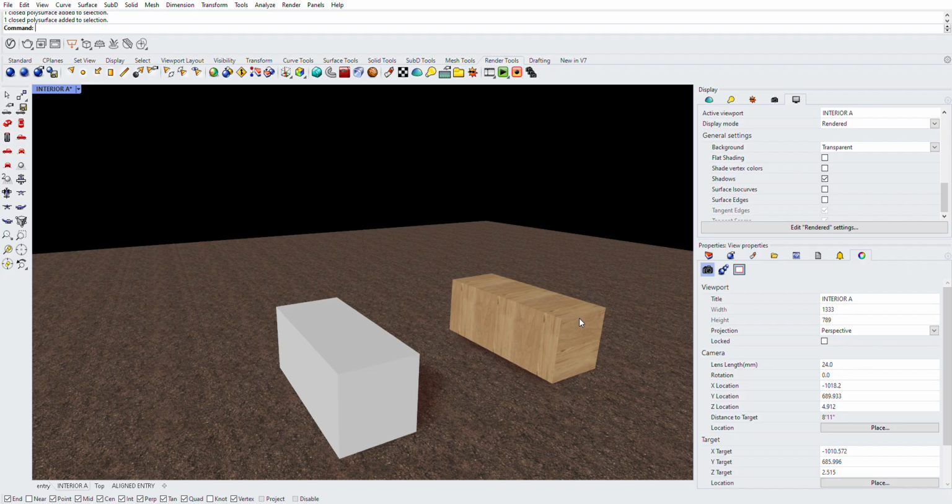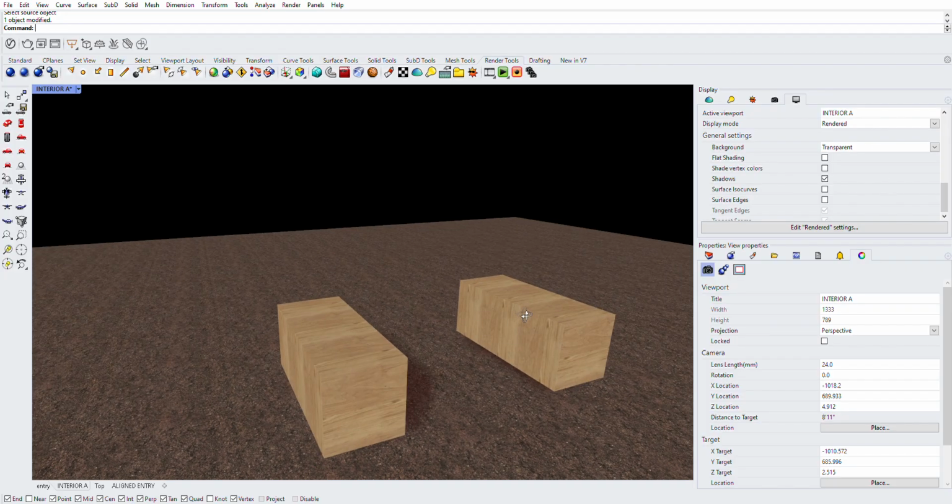if you guys remember with line types, you can do the match layer command. A really useful one for bringing materials across is the match properties command. So basically I want to get the information of this box onto this box. I go match properties, I select the object to modify, enter, I select the source object, enter. And it's going to do all of these different characteristics, the big one, of course, material. So that brings that across, great.